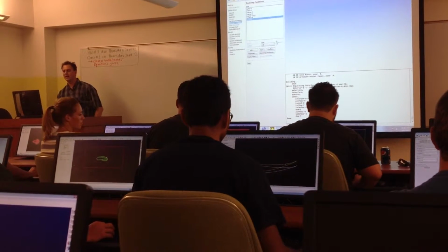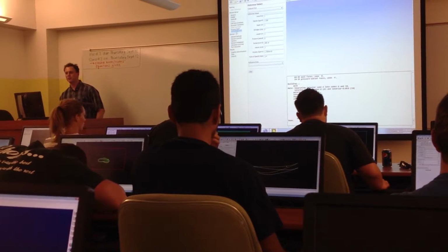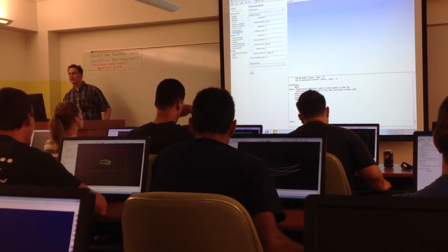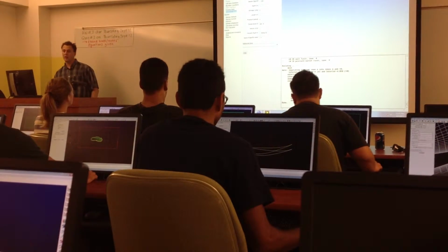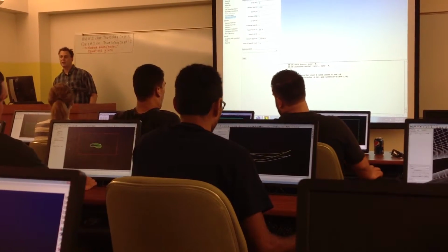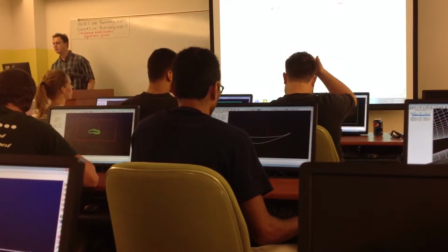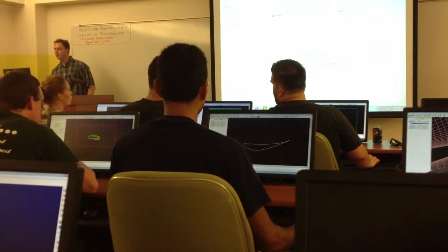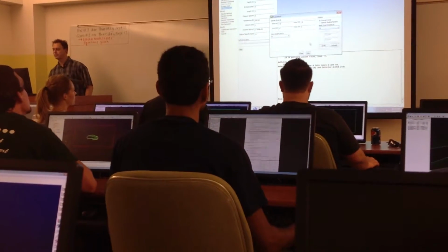We're not doing any adaptation yet. Reference values, important to set. What's the area? I fixed the mesh. We think it's read in English units. It's in inches, right? So let's go to scale. Go to mesh, scale, and here, specify. Mesh was created in what? Inches.